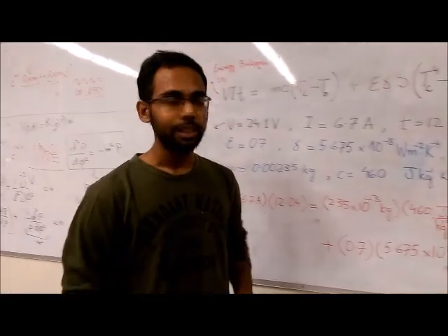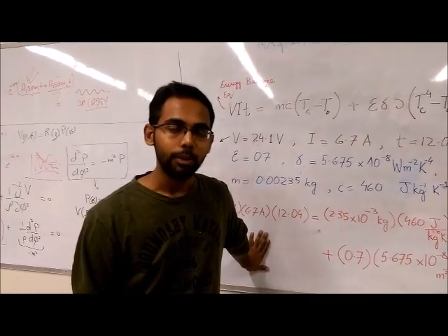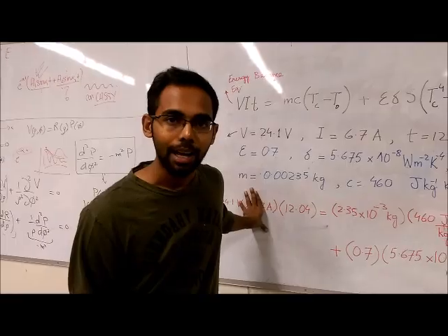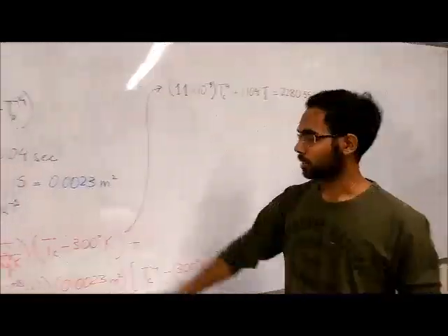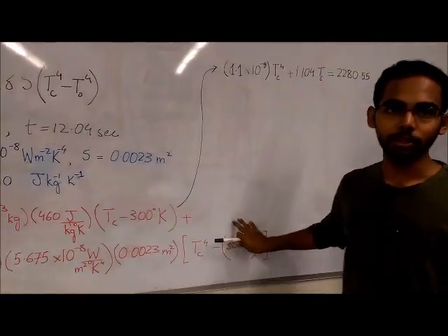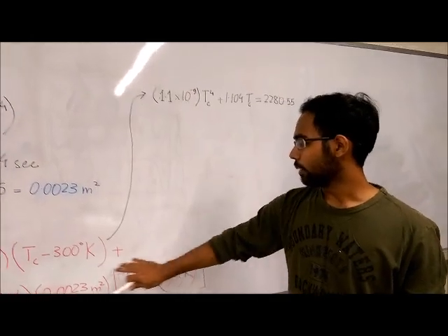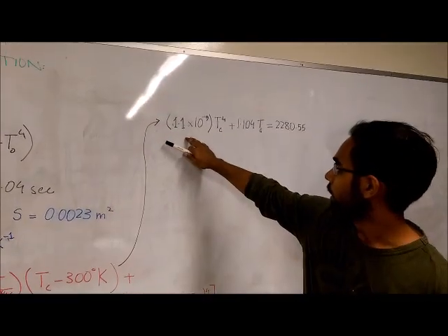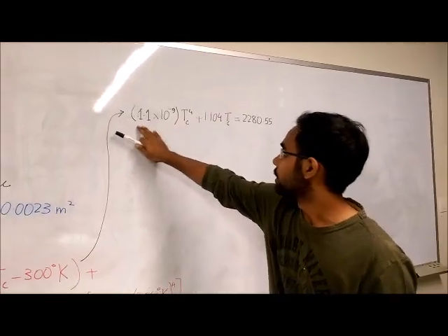But as we can see, this is a very tedious equation to solve manually. So what we are going to do right now is plug these equations into MATLAB and let it solve for Tc automatically. Even though we are going to solve this in MATLAB, we should at least simplify it so that we can have a familiar form of an equation. So what I did was manipulate all of these values to finally get one single polynomial equation of order 4, which looks like this.